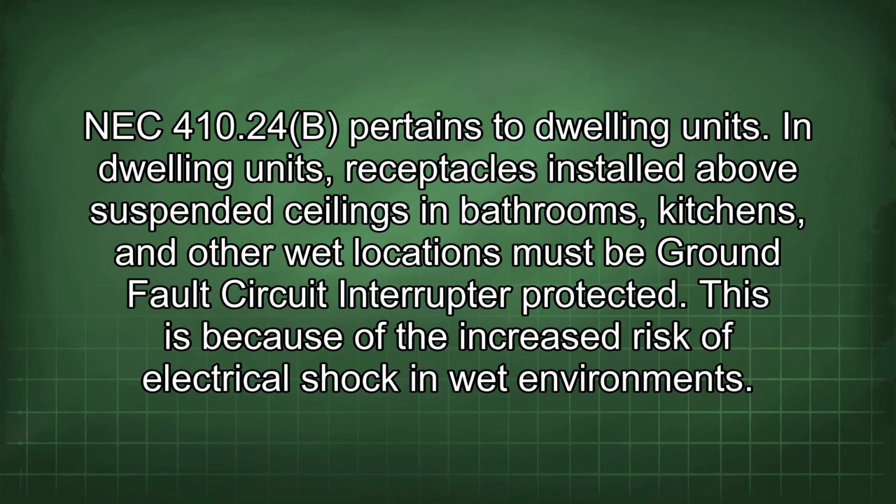NEC 410.24b pertains to dwelling units. In dwelling units, receptacles installed above suspended ceilings in bathrooms, kitchens, and other wet locations must be ground fault circuit interrupter protected. This is because of the increased risk of electrical shock in wet environments.